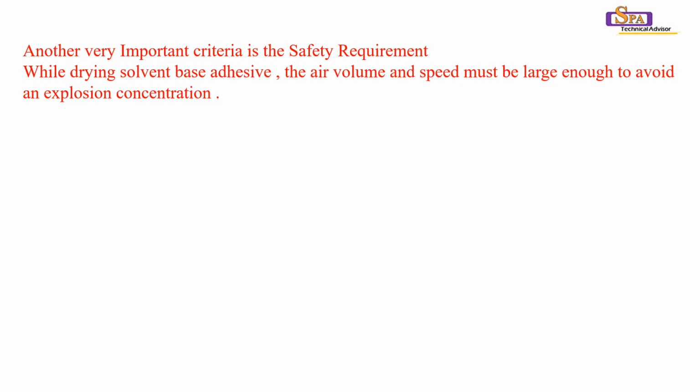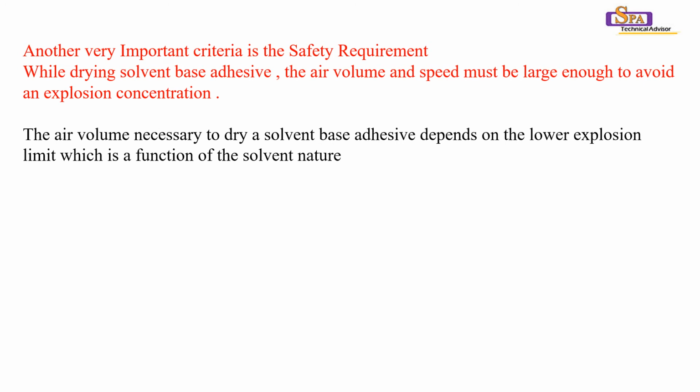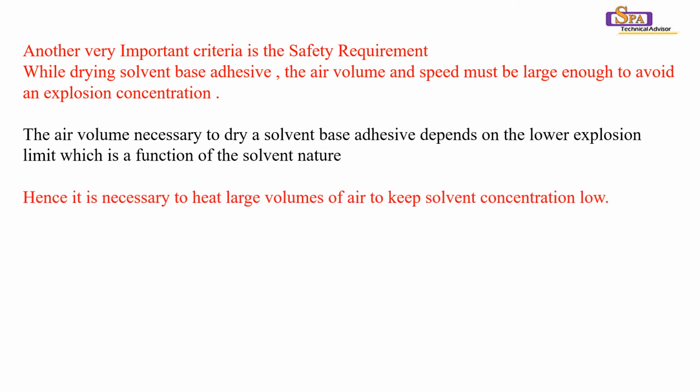Another very important criterion is the safety requirement. While drying solvent-based adhesive, the air volume and speed must be large enough to avoid an explosive concentration. The air volume necessary to dry a solvent-based adhesive depends on the lower explosion limit, which is a function of the solvent nature.